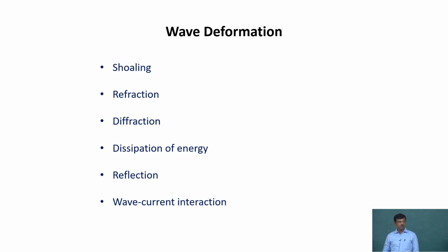In the near shore there are many processes: refraction, shoaling, diffraction, and one important thing, the dissipation of energy, that is wave breaking. It transfers the entire energy or momentum to the entire water column, because energy cannot be created or destroyed. The released energy works to lift the sediment or transport the sediment from one point to another. That is what wave breaking is, one of the very important parts of the entire coastal process.